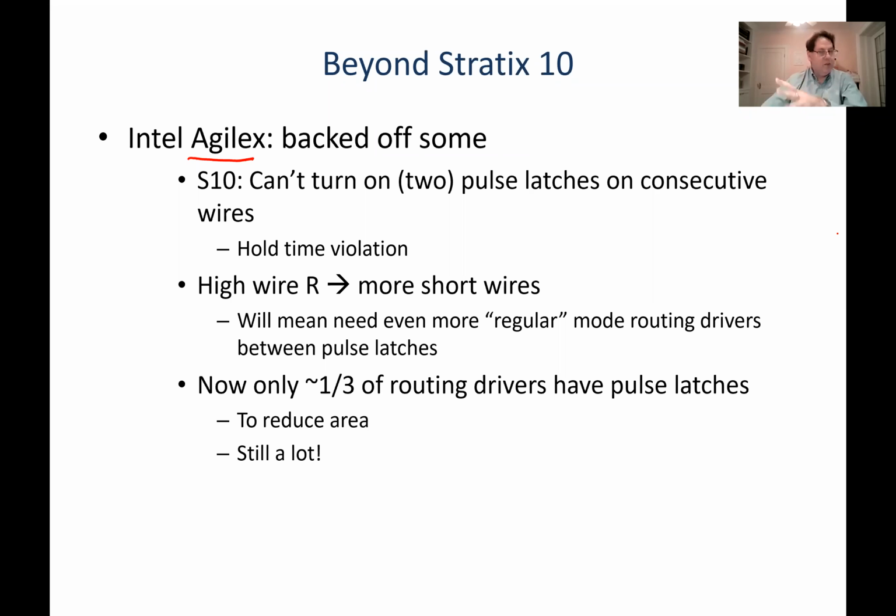They have a lot of flexibility about where they want to put registers in their CAD flow because they have so many of them, but they can never actually use all of them because it would produce hold violations. If they use a register on this routing wire, then they need to have at least a couple of routing wires after that before they use another register. So this routing driver could be a register, but the CAD tools are not going to allow it because it'd be a hold time violation.